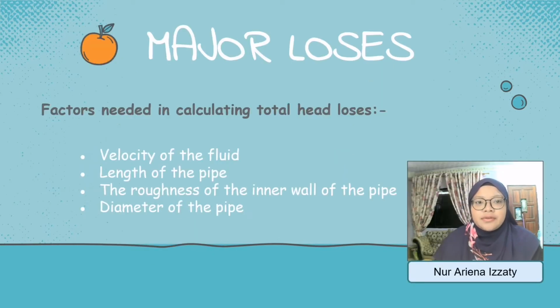Major losses. For an incompressible fluid through a pipe, there is always a creation of a friction force along the pipe wall against the fluid. In this experiment, the theory used is the loss of energy and the total head of fluid due to the frictional resistance of real or viscous fluid. In fully developed straight pipe flow, energy loss or head loss occurs due to the wall friction.